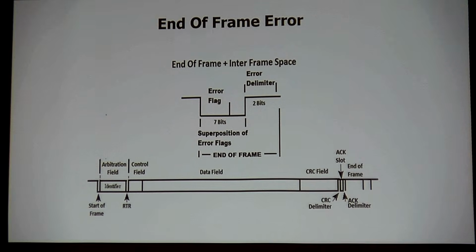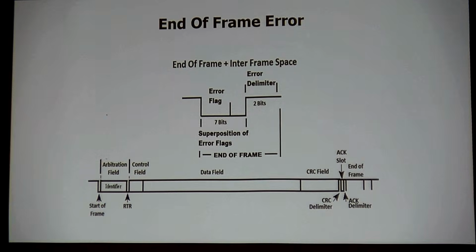Now let me tell you, this is really important right here, because this is what really happens on the bus. The clocks get off. And when the clocks have a problem, or the temperatures are different, and my edging isn't correct, I will run a CRC, being another module, and I'll see it came up wrong, and I'm going to put a bit right here, an error delimiter, and I'm going to destroy your frame. Except I don't get counted for it. I ruin your message, but no one counted me. Who got the bus? Oh, I'm the ECM. We said that was the identifier in the arbitration field.